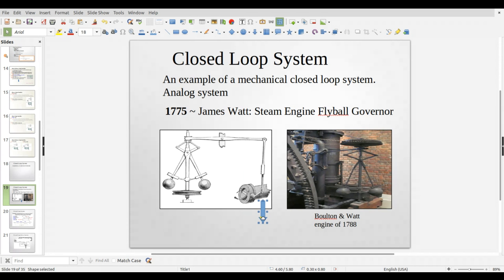All right, and so most of the time, we could do some kind of control like this using a PLC, and it would not go unstable. But remember that with that delay, you do have to be careful that if that delay is too long, you could add some severe instabilities into the system, where instead of the system moving nice and smoothly, it starts reacting kind of violently to any disturbance in there.